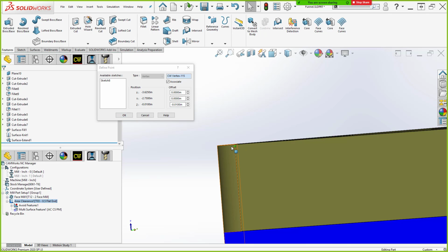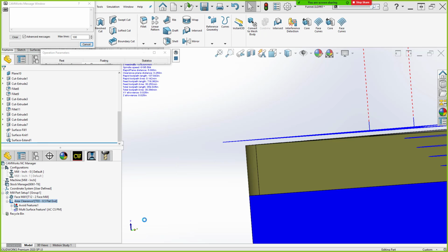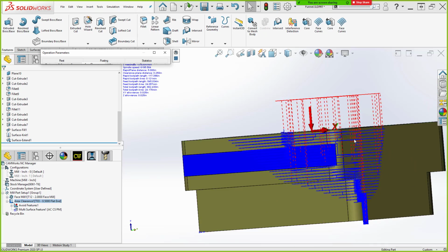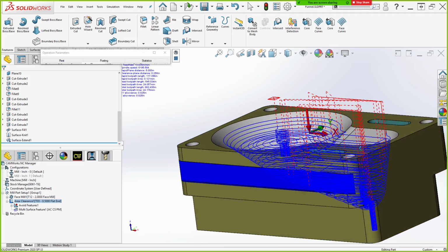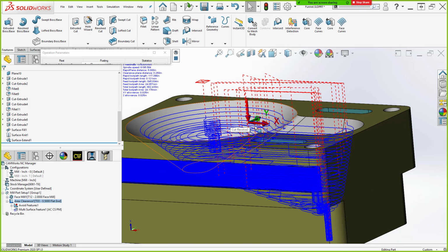You're setting an upper Z limit. No toolpath allowed, no cutting toolpath allowed above that point. You'll still have entry methods and plunge methods. But once again, this is a hell of a lot quicker than trying to do work in progress. It's even potentially quicker than contain and avoid areas, depending on the complexity of your shapes and things. Right? So another method of doing, we've done this 3 different ways now of controlling this toolpath.